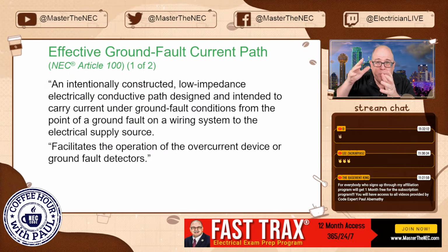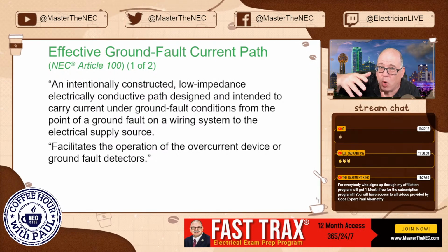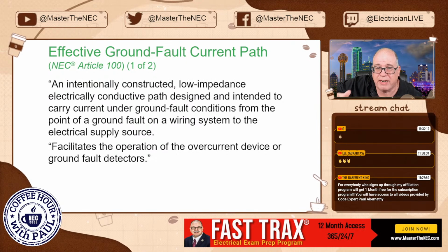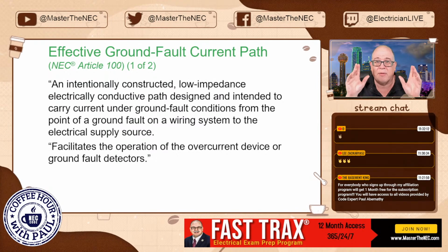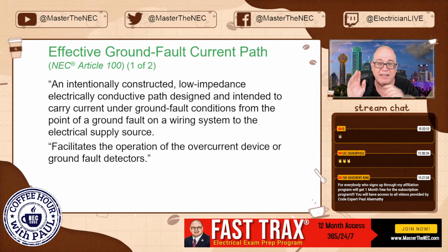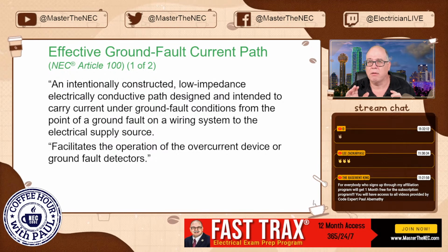So if you have something pouring molten metal, the last thing you want is, as it starts to pour, to have the breaker trip and then have it come out and spill all over people that are near it. So we want to have it continue its process and then have somebody that's trained to say, warning, warning, warning. We need to let that get to a safe position, and then we can safely shut it down.